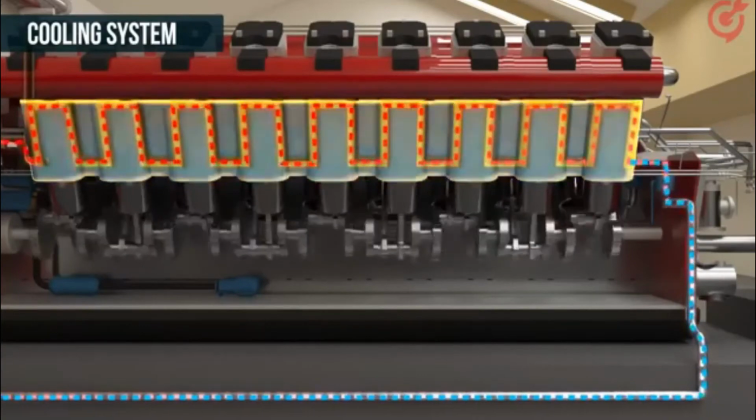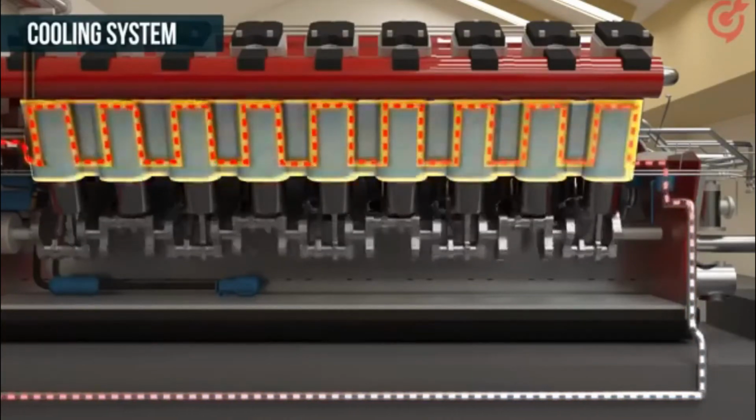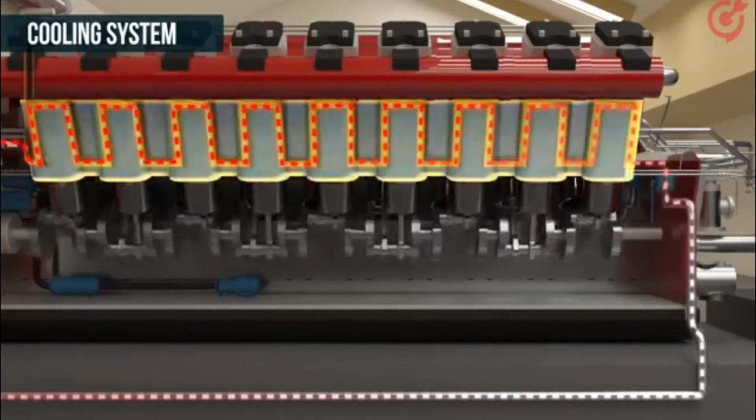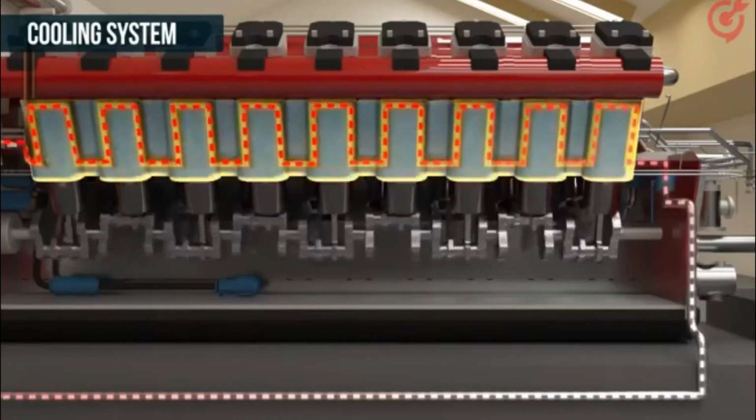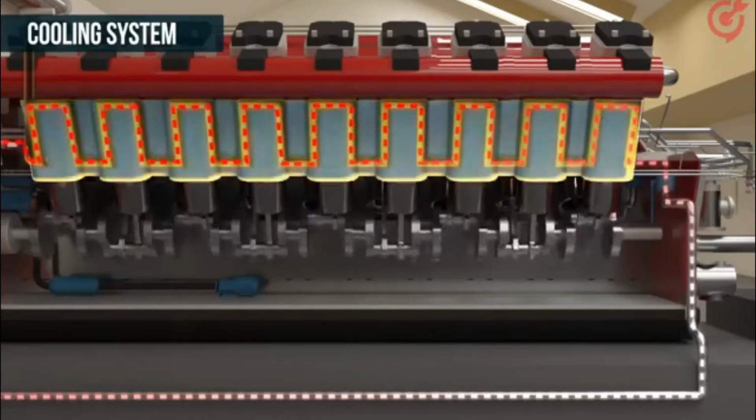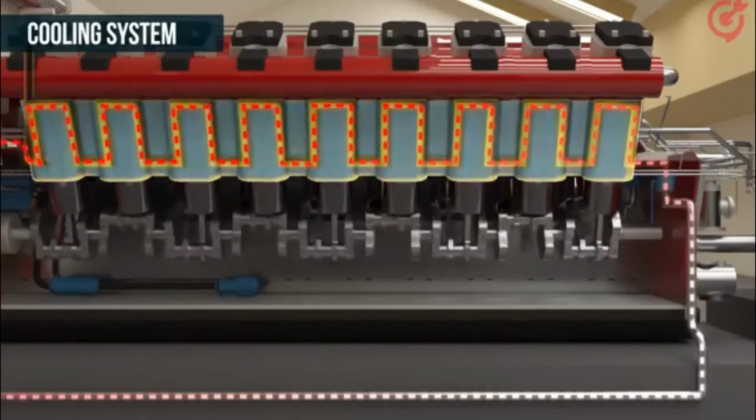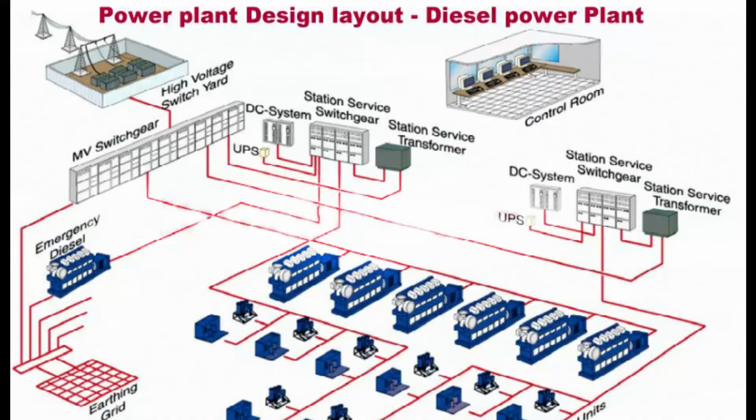The advantages of diesel engine plants include low capital cost, quick installation, high efficiency, waste heat recovery, quick start, suitable for small remote communities, and suitable for peaking duty. The disadvantages include high fuel cost and environmental emissions issues, and high noise, of course.